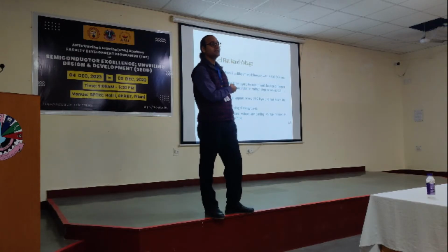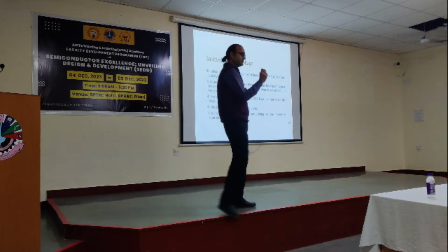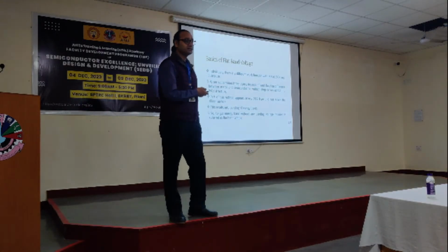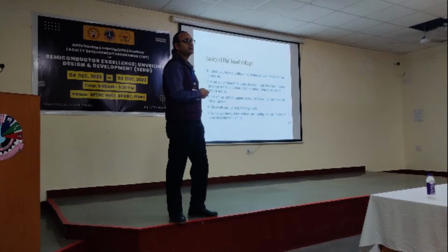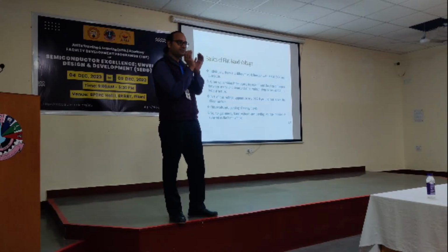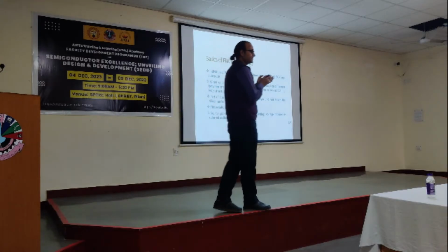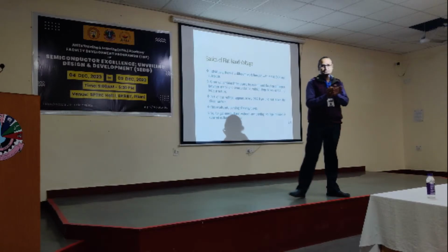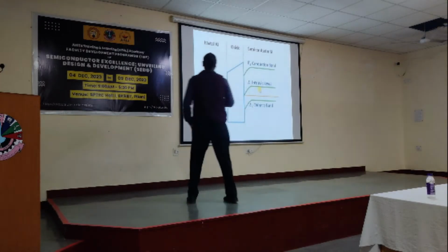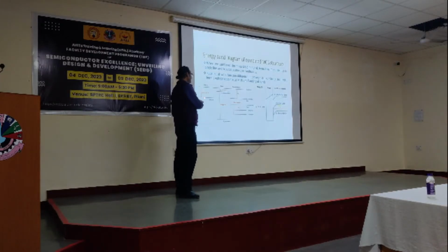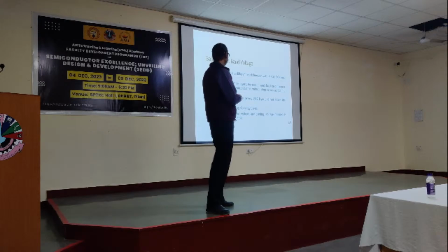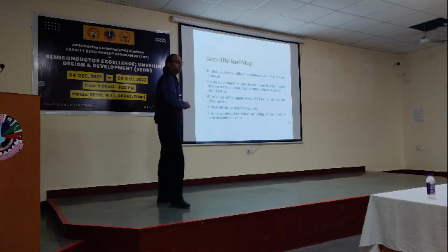Now we are not in an ideal situation. What was the ideal situation? When the Fermi level was the same for the metal as well as the semiconductor, right? Now we are in a practical situation. So how to get the flat band condition? What will be the first gate voltage? The first gate voltage required to be applied at the gate will be the difference between the work function of metal and semiconductor. I hope you are getting this point. The first portion will be this one, the difference in the work function of metal and semiconductor. Okay, so that is the story about flat band.